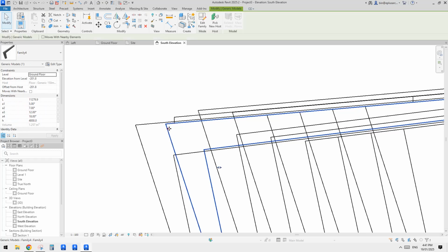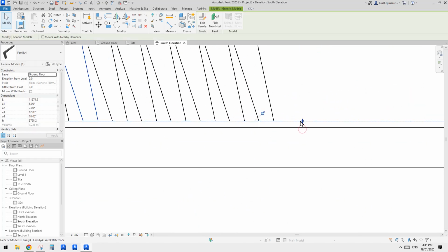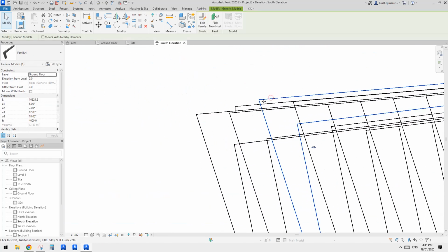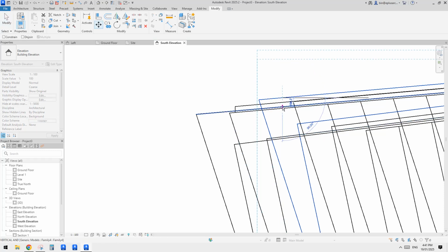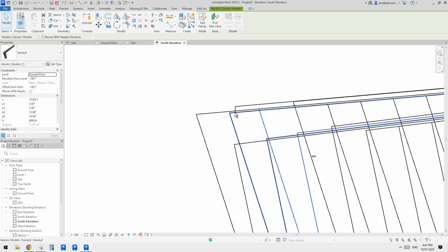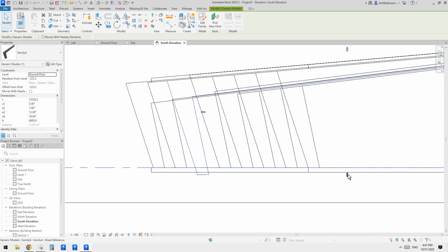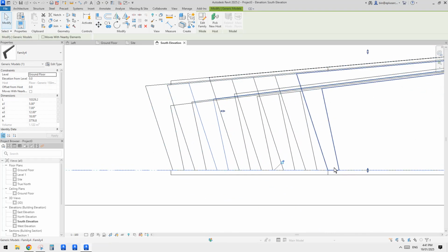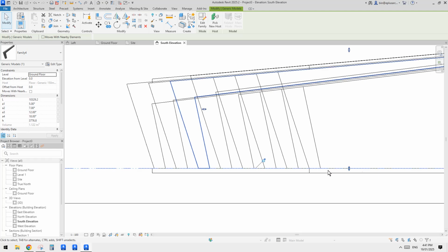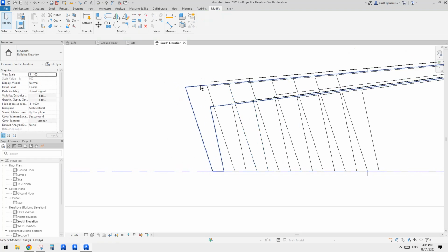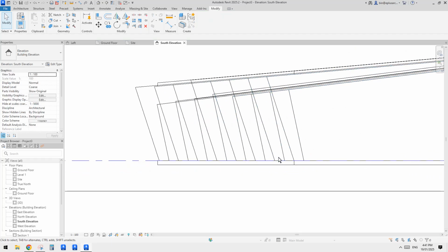And then we just need to go here and drag this onto a level, right? So it's very simple. Again, select this one, go down to the underneath of the roof, which is, sorry, not there, here, right? And then we can just drag this up to align with the floor, because they are all horizontal. It works because they are parallel with the direction of that reference plane.